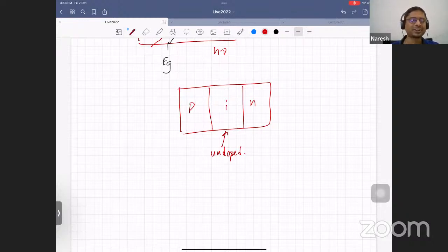Sorry, no, that's not what I mean. Essentially, when you shine light, you want to create electron and hole pairs. When you have an intrinsic region, the generation rate is going to be high. So you get much better efficiencies in photodetection. If you have doped, well, the story is not complete there, but it's a little bit more complex. Let's not get into that, because we'll have to think about a lot more factors, like how the curvature of the bands are and so on.